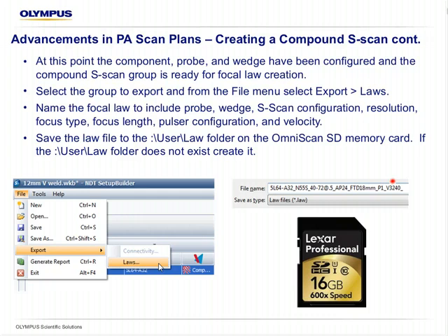With a few common configurations on the flash card, most ANSI piping range can be inspected without having to go back and forth from the calculator. It's normal to develop a library of these and enforce them in the work procedure. So we want to remove as many decisions from the inspector as possible and move them to the work procedure so consistency and best results are optimized.